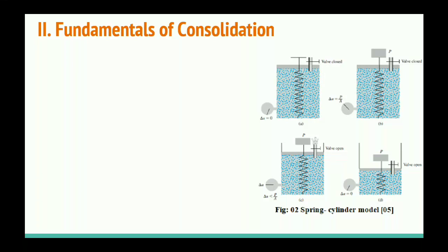So initially when no load is applied on the piston, the spring and the water are initially free of stress. It means the pore water pressure will be 0 and the load registered by the spring will be 0.